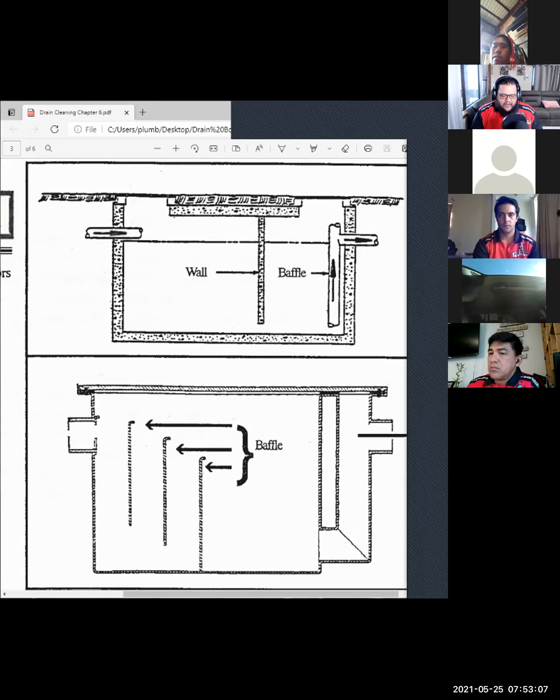When you're on site, you see everything backing up. First thing is find out what's backing up. You see a floor sink, and then you walk around the rest of the restaurant. You check the other floor sinks. Is anything else holding water? If not, then you're dealing with just that one fixture. If you're walking around this kitchen and everything's backed up, that's when you walk out to the trap. Pull the first manhole on the trap. Look inside. If you see the inlet pipe still exposed above the water, you're dealing with a mainline stoppage before the trap.